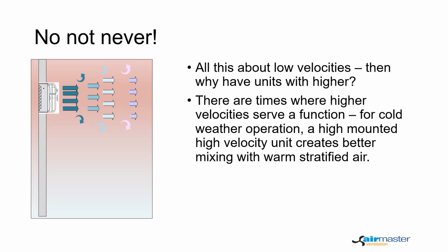Hot air rises, which is why there are such things as hot air balloons. But it rises even without the balloon around it, and it will stratify in your building with the hottest air near the ceiling. There are a number of good reasons that you might want to operate a supply fan year-round. But the challenge is that you don't want to blow cold air on anyone. A high-mounted fan with a somewhat higher velocity is a good solution, since the velocity is going to cause mixing with the warmer air before it descends to floor level.